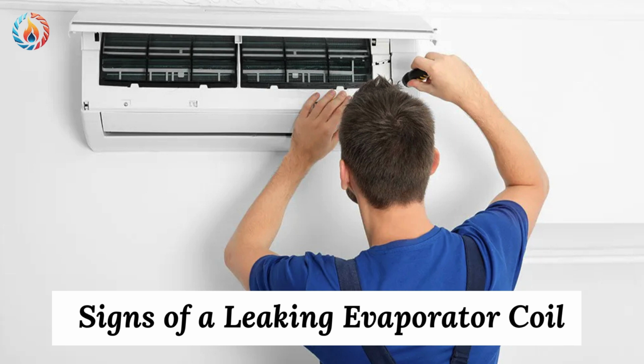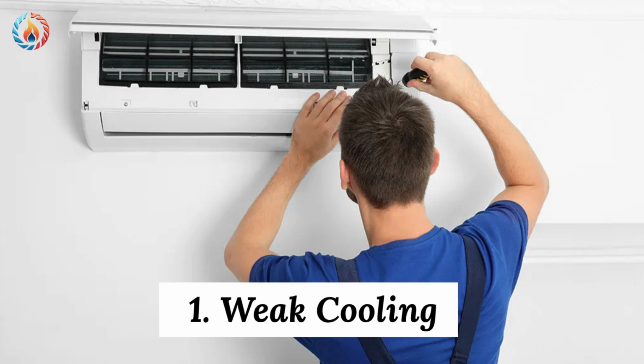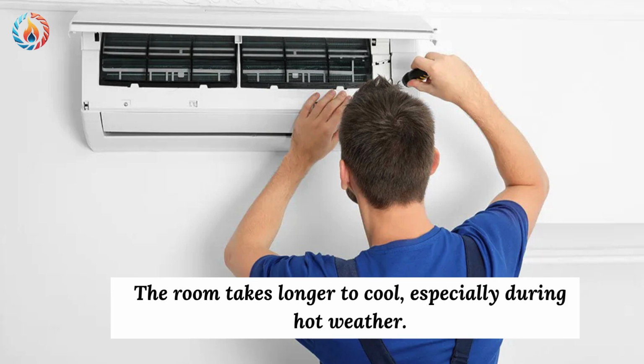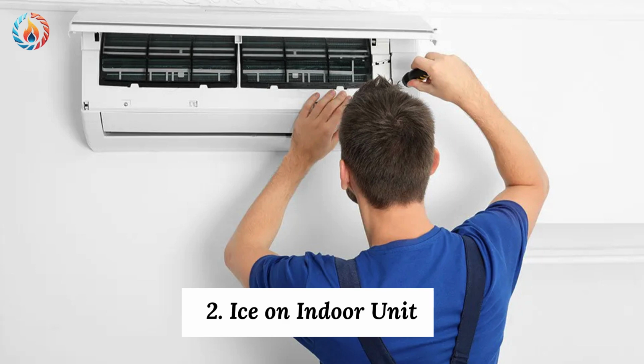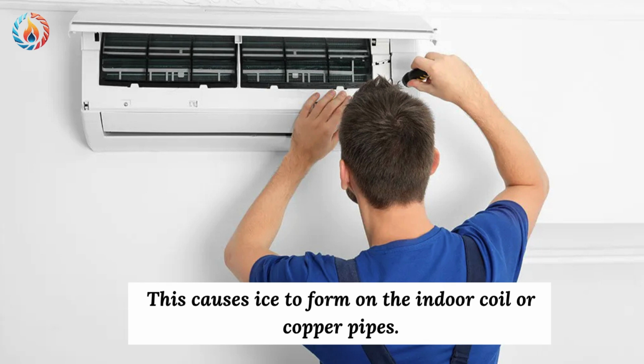Signs of a leaking evaporator coil. Now let's talk about the warning signs. 1. Weak cooling. If your AC is running but not cooling properly, refrigerant leakage may be the reason. The room takes longer to cool, especially during hot weather. 2. Ice on indoor unit. Low refrigerant pressure can make the evaporator coil extremely cold. This causes ice to form on the indoor coil or copper pipes.